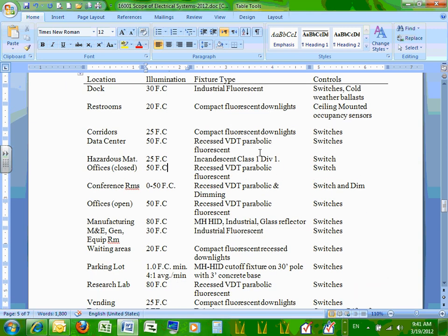I want to remind you, Phil, that this building does not have a lighting control system. We do not have a lighting control system in this building, meaning we don't have a lighting control panel. You can have an occupancy sensor. If you don't have a lighting control panel, how would you have an occupancy sensor? It's running through a power pack, just a standalone relay in the ceiling. But there is no full-blown lighting control panel like we have done in other projects. If you want to do it, you can, but it's not required.